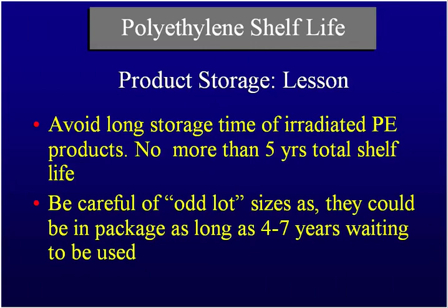So the lesson here is you want to avoid long storage times of radiated polyethylene, no more than 5 years. Be careful of odd lot sizes, as they could be packaged for as long as 4 to 7 years waiting to be used. Okay.